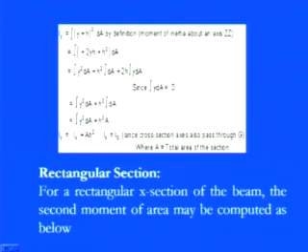So, the integration of (y plus h) whole squared dA will give you Iz. Again, we can expand it as y squared plus h squared plus 2yh, into dA. Since y is measured from the centroid, the integration of y dA will give you 0, because there is no deformation within that particular element.